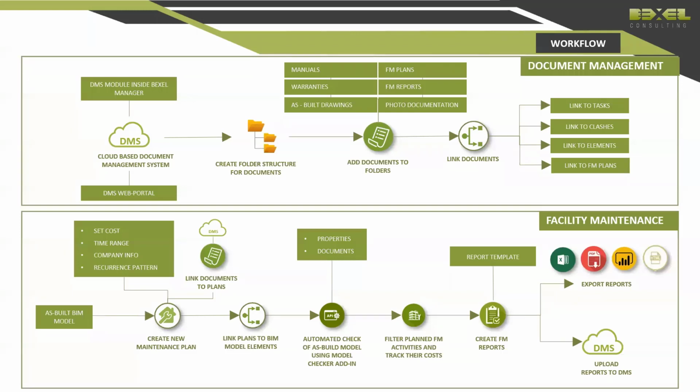So briefly, BEXEL Manager can not just access and store BIM models and their geometry, but as already explained, you can use BEXEL Manager to read information provided within the BIM model, or you can create additional information, properties or metadata in order to enrich the quality and the level of information of your BIM model. All this information is stored, and it can be additionally upgraded with documents.